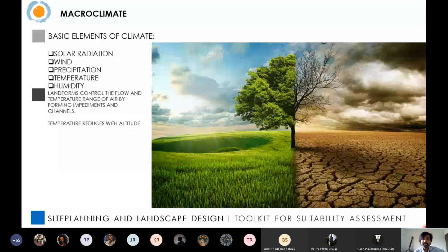But be aware that in landscape, landform, the lay of the land can actually affect the flow of the air, so it can affect temperatures, it can affect the perception of heat, it can affect humidity. For example, if you are building in the coastal environment, one of the most effective ways of creating a conducive, built or unbuilt environment is to ensure ventilation, because we have high humidity.